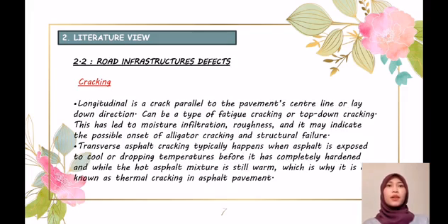Cracking. Longitudinal is a crack parallel to pavement center line or lay down direction. Can be a type of fatigue cracking or top-down cracking. This has led to moisture infiltration, roughness, and it may indicate the possible onset of alligator cracking and structural failure.